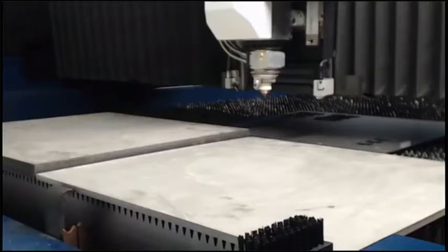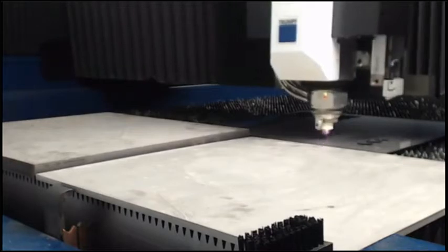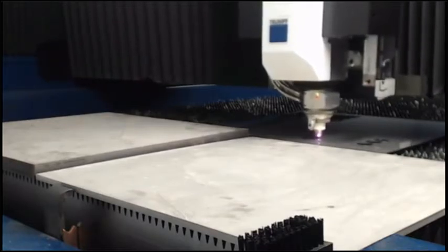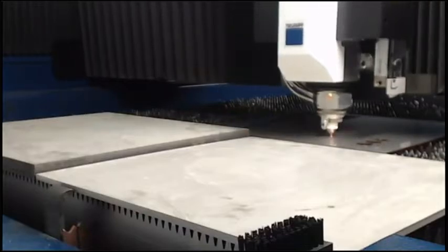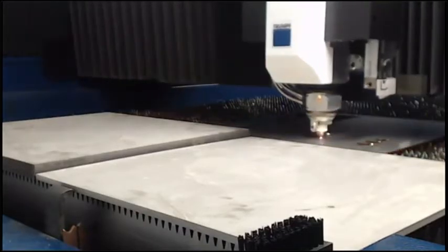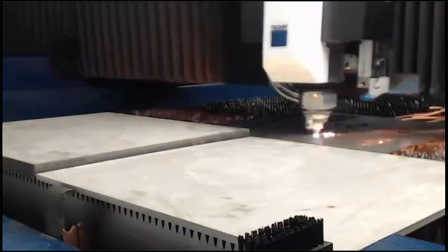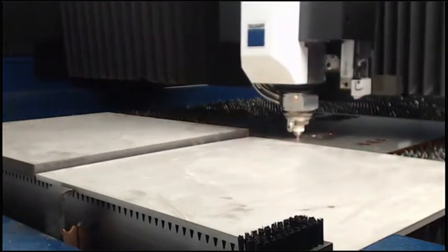All right, guys, we're all set up and ready to go again. Sorry about that. So now you can actually see what I'm talking about. There's the laser etch right there. And again, this is nitrogen cutting. 826 inches a minute on 1/8 inch stainless steel.